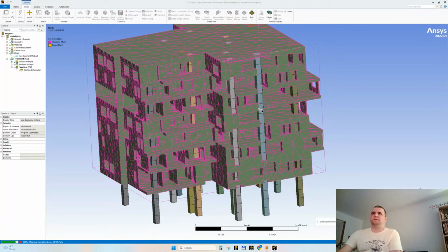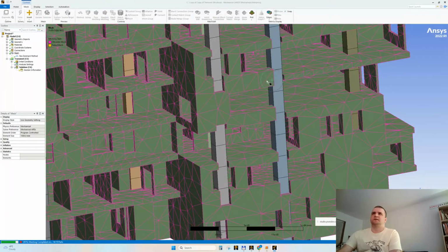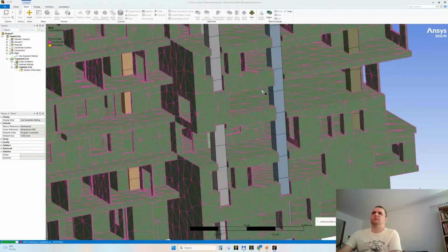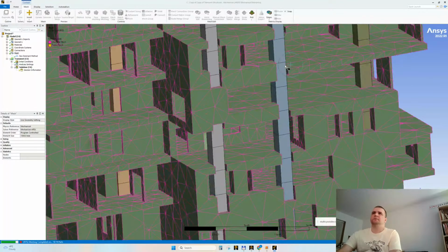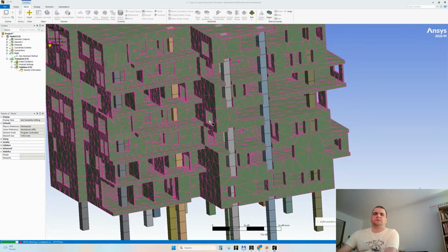If we leave such big elements, the nodes will never meet. Yes, we need these nodes to meet, and it's kind of absurd, you know. We need to impose a pinball radius, a big pinball radius. So this is why we need a finer mesh after all. I will refine the mesh in the columns separately, I think.